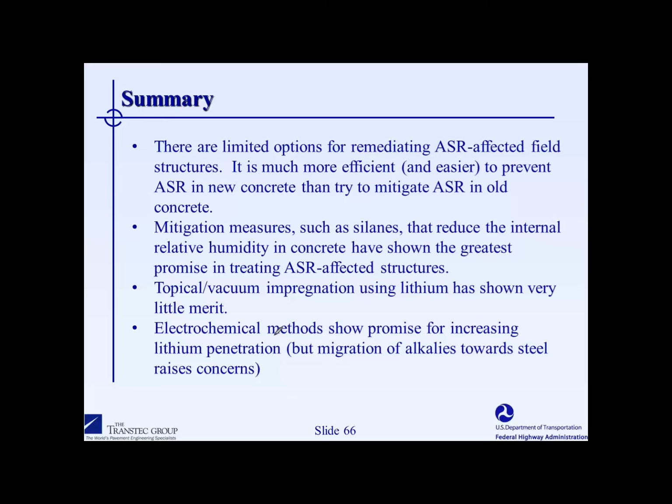Okay. Another question we had was, do the silane treatments have to be renewed every so often? Well, that's a great question. Some of the literature from the manufacturers will recommend some reapplication rate, say every 5 years or so. The experience out of Canada with the Jersey barriers shows that the efficacy has been well over 10 to 15 years now. So I don't think we really have a definitive answer on that at this point.